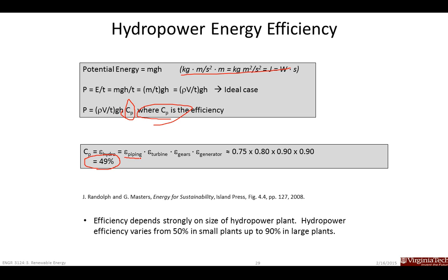It depends what type of flow rate you're looking at. The faster the velocity is, normally the lower this number is. If you have something moving 1,000 miles per hour, this friction factor will change dramatically versus if it's moving at 0.0001 miles per hour, because the friction will be severely different, as you're looking at turbulent versus laminar flow and things like that.